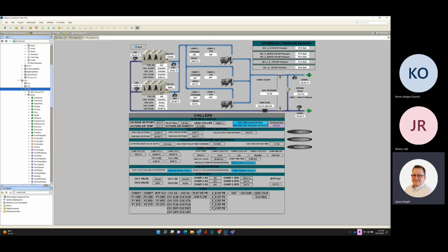Yeah, can something be done about it? Yeah, probably. Maybe I add some logic that says, increase the bypass min position at 4:30 every day from 10% to 35% as the minimum, just so it doesn't trip the machines when everything goes unoccupied. But like I said, I'm trying to learn the personality of the building and how fast everything shuts down and closes. We're still figuring that out.